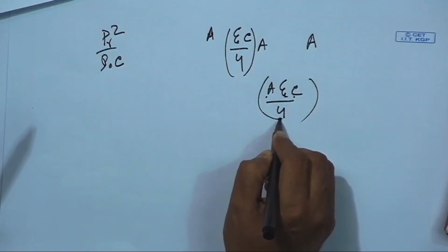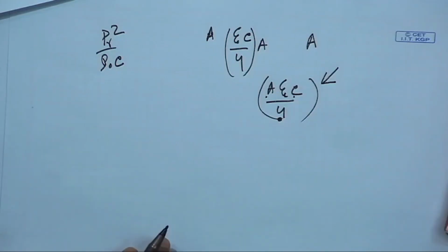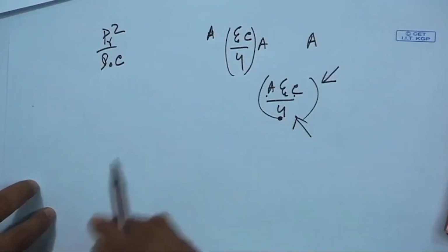Understand or not? If this much energy is absorbed, the rest of the energy will be reflected back. That reflected energy will develop the sound field in this room, added with the direct sound. That means, if I switch on the microphone, my loudspeaker, for some time and then switch off, then what will happen? Multiple reflections from different directions will come and develop the sound pressure level. So the energy which is absorbed plus the rate at which the energy is developed in this room is equal to the total energy.